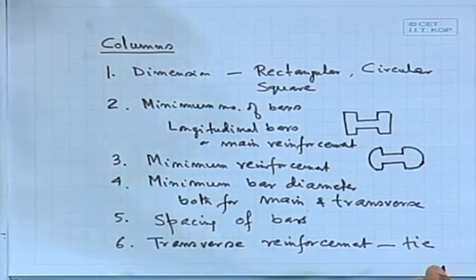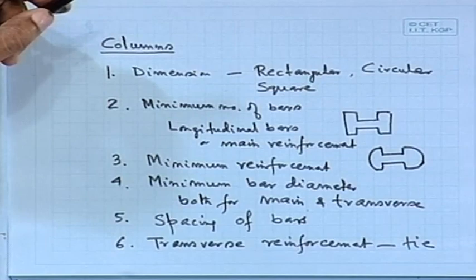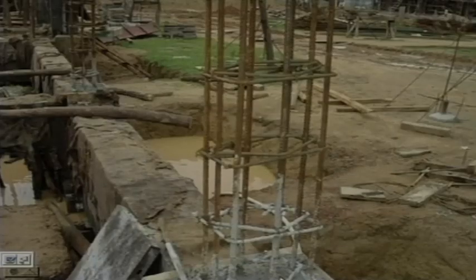This transverse reinforcement we call it ties. Compared to that, your stirrups, here we call it ties. So, ties mean this is the lateral reinforcement that you have to provide. So, this is the ties we are providing here. Personally I do not like this type of arrangement. Generally we provide whatever the gap, instead of providing here, I prefer one along this, the other one with a little gap here, that I shall tell you in due course. That will be easier to make, because anyway it is also correct, but it depends on how fast you can make the workmanship. That is why we can put it the other way. So, detailing is also not a unique solution, you can have a number of solutions.